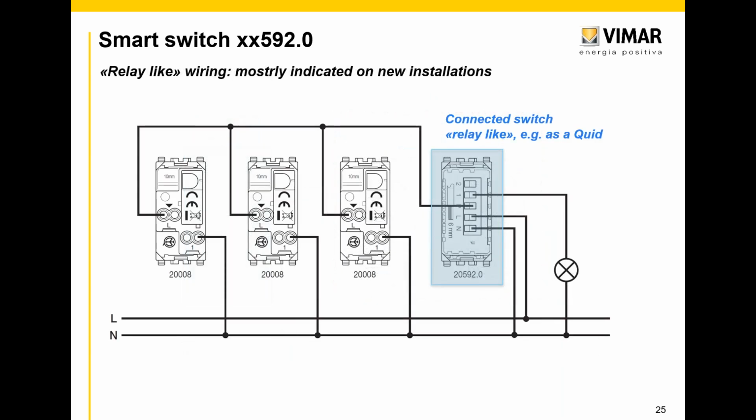The other solution we offer, and this is something very good and distinctive against some competitors, is that we also have the P, the push button input. This push button input allows the installation we call relay-like. So the output to the light is just one. Just connect output 1 directly to the light circuit, and then to the P terminal connect N standard push buttons. In this situation, all the push buttons control the light like a relay.